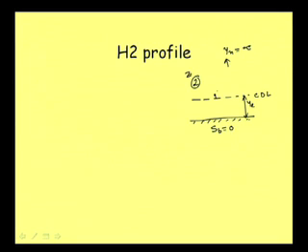Well, if we get a profile here, this will be a drawdown profile, as we know from our earlier understanding, but still we need to explain it. And if we say that this is the depth y, here we can say that yn is greater than y and y is greater than yc.